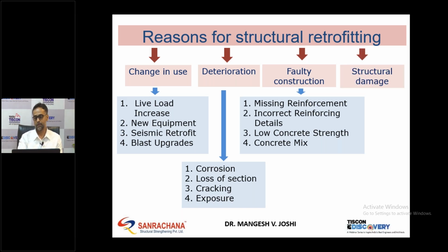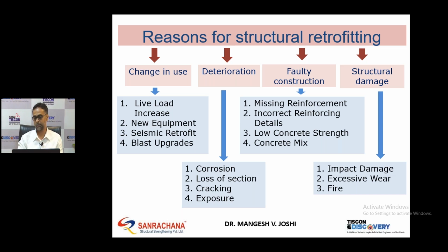Then structural damages. Structural damages are mainly because of impact, excessive wear, and fire. At least in a year we come across 3-4 different fire-damaged structures where concrete gets damaged because of exposure to high temperature, and we need to offer some solution. So this covers the domain of structural repair and retrofitting. Normally we have to offer solutions in these types of situations.